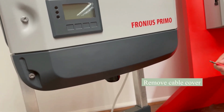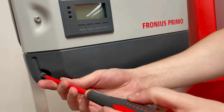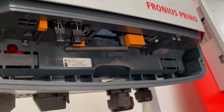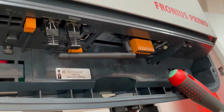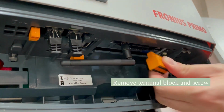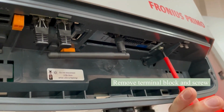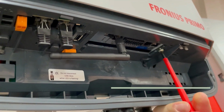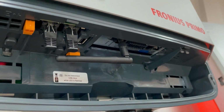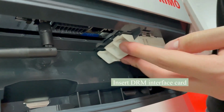So the next step is to remove the two screws from the base plate to remove the plate itself. So we undo both of them like so, and the plate will come out, and we'll be able to see underneath there's an orange terminal block, and the data manager card is already inside. The first thing we're going to do is remove this terminal block, and then undo the screw here. And that'll come out.